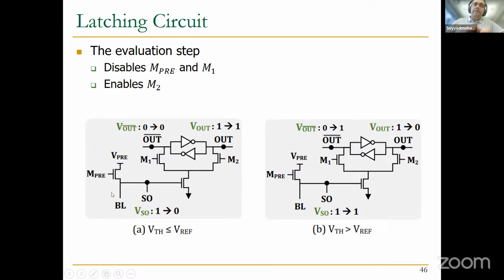So if that flash cell in the bit line is not programmed, and it's erased, then when you apply that VREF, it is going to connect this bit line to 0, to the ground, and because of that, this capacitor will be discharged. So this will be discharged, and this transistor will be off, because there is no high voltage in the gate.